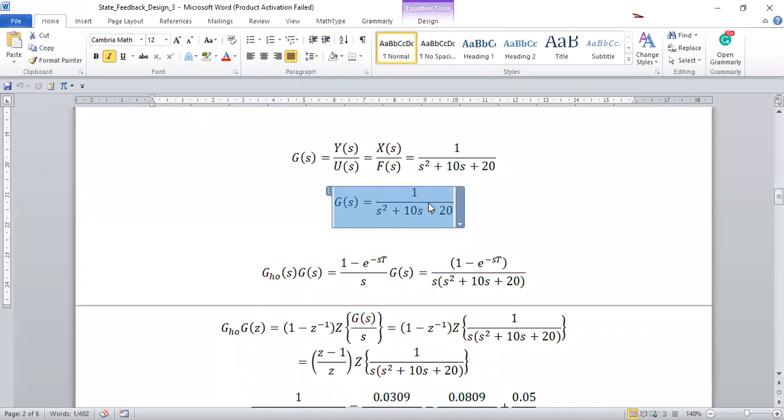It sees the system in discrete time units, and it uses a zero order hold to convert from the discrete time domain into the continuous time domain, which is what is available in the real world. So we need to represent the system exactly the way the computer sees it.